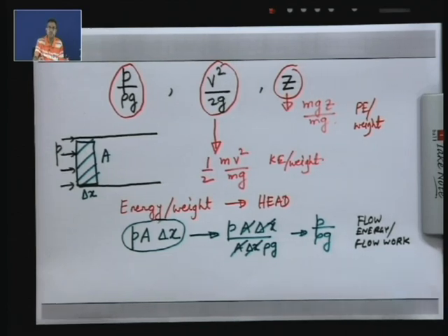This packet of energy that we are talking about here is mechanical energy. In the mechanical energy we have three components: the kinetic energy, the potential energy and the flow energy. Normally you have only the kinetic energy and the potential energy, but where from do you have the flow energy? Because it is a moving, flowing system, it must maintain the flow in presence of pressure. So, it must have some additional energy beyond the energy of a stagnant system.